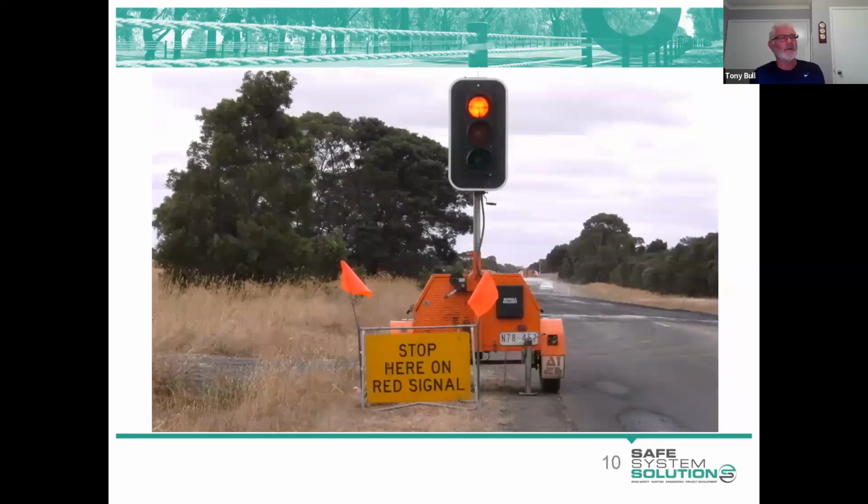Also, this again is not a game changer, but it's the incorrect use of the signing. The stop here on red signal, that's fair enough. It should be 6 metres away from the traffic signals. I don't know whether it's 6 metres or not, could have been. But the lettering on the background is incorrect. I'd say the sign manufacturer thought, well, roadwork signing is black writing on a yellow background, let's do that.